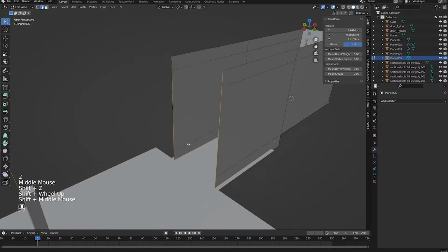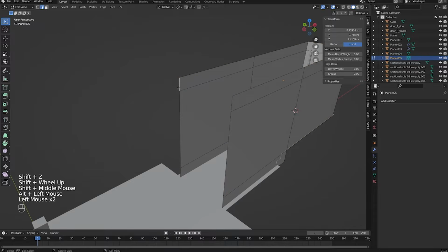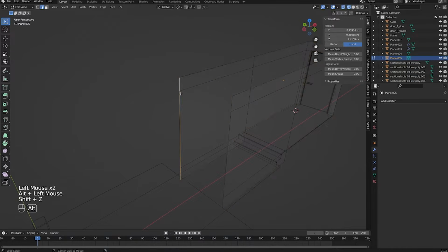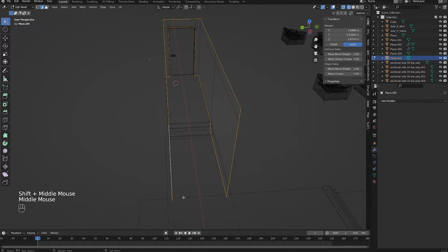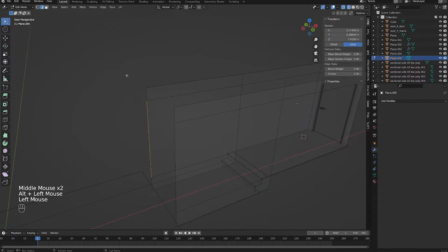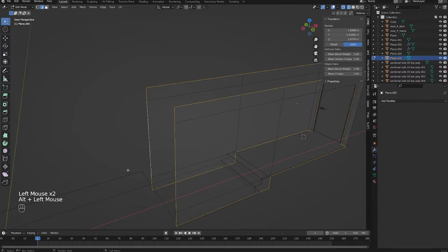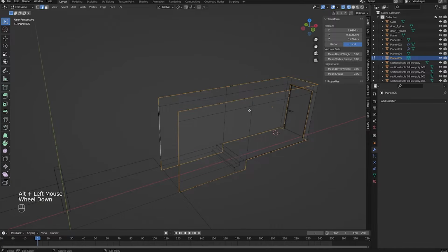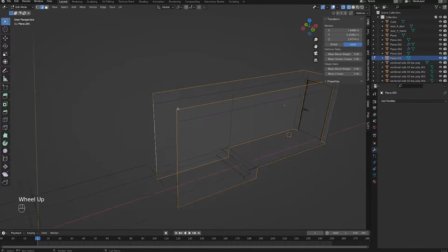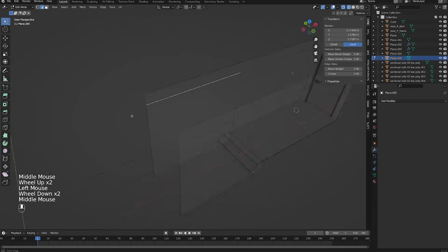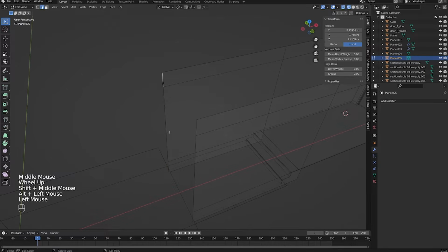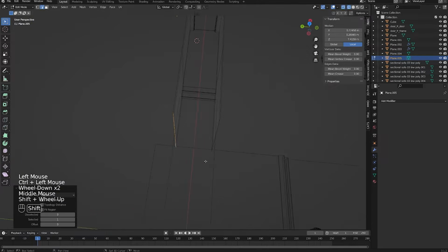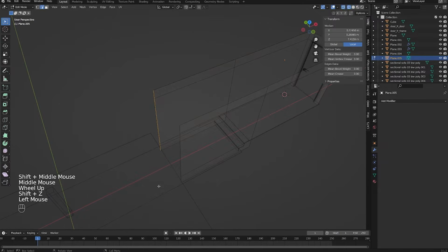And I think this will do fine. So let's just select this edge now. If I do Alt edge select and I select all those edges, you'll see instead of just doing this, it now selects all the edges, and that's just the way we've extruded this. It makes the program think that all of this is one loop, which it kind of is. So we can't use Alt, but we can still select the edge, press Control, and go all the way down there, or just select all of it manually.